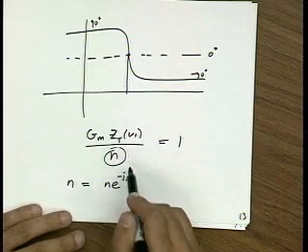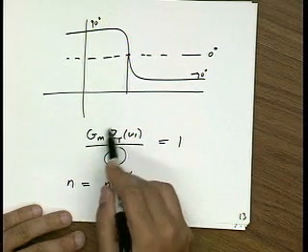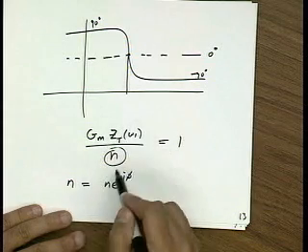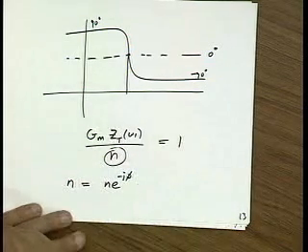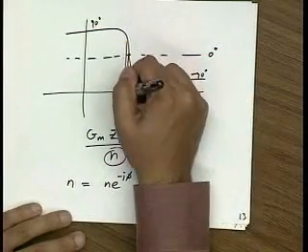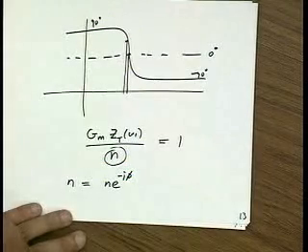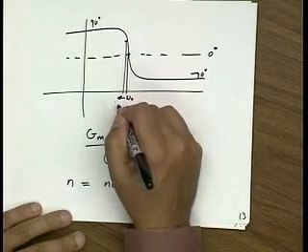Then that phase delay has to get compensated, because now this is complex. This now needs to become complex, so that overall the loop gain is 0 degrees exactly, right? That means I'm going to have a little bit of phase advance from the tank to compensate for that phase delay. So my frequency is going to shift away from omega naught.